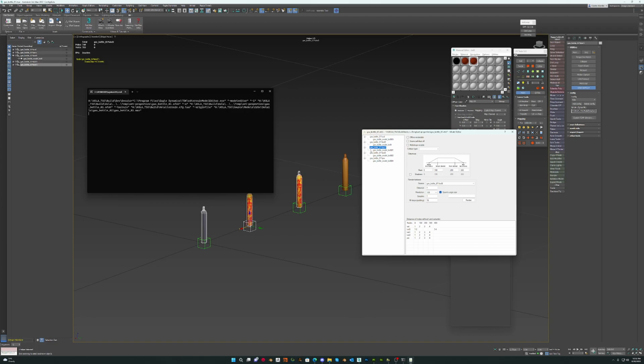We've got LOD 1. Now rule of thumb, for LOD 1, the first two, near distance and near blend, should always kind of be 100 lower than the maximum value of LOD 0. So LOD 0 was 400, so it's kind of 400.